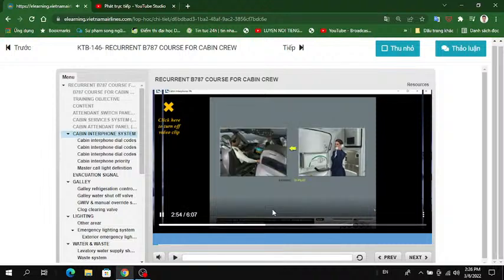A normal two-way call to the flight deck may be made by any station. A cabin call message appears on the ICAST display on the flight deck, and a chime sounds. Pilot Alert connects the caller to the flight deck and is used in emergency situations. Pilot Alert calls take priority over all other calls. Other stations can use Pilot Alert simultaneously and will be connected on the party line. A cabin alert message shows on the ICAST display on the flight deck.